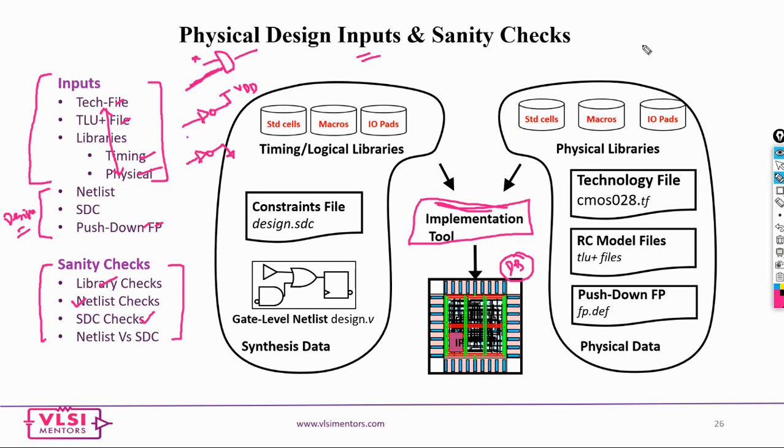And then SDC checks. So you have flip-flops, correct? So do all the flip-flops in the design get a clock? Okay, so you have a clock signal, but this is something that is missed here. There is some kind of breakage. Breakage in the sense this net is not defined, or probably for some reason it went away.